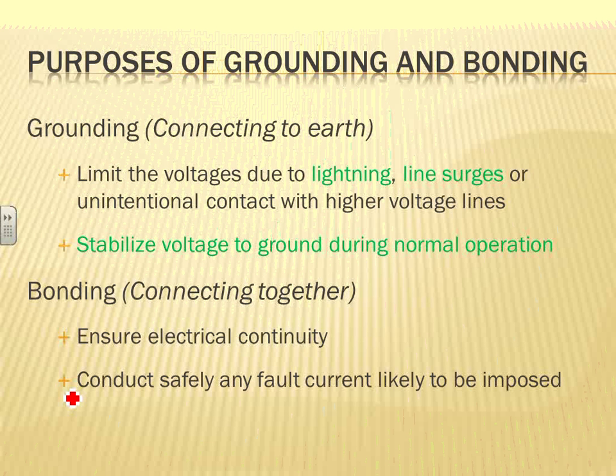Delta, guys, if you have a lot of surge, voltage surges, or a ground fault, it can create a big surge in the voltage and burn electronic equipment. A surge in the voltage on a delta is not as easily absorbed as in a grounded Y. So that's why we'll talk about the advantages and disadvantages of a grounded system or ungrounded system. Let's get into it now.